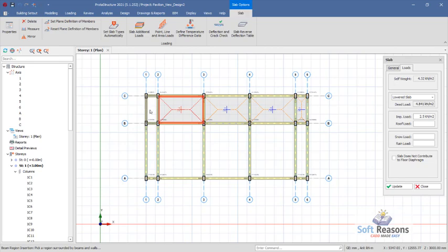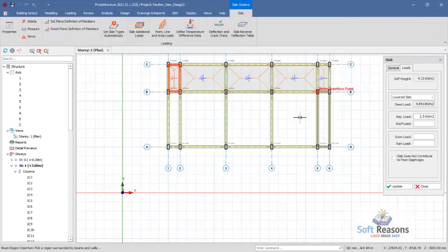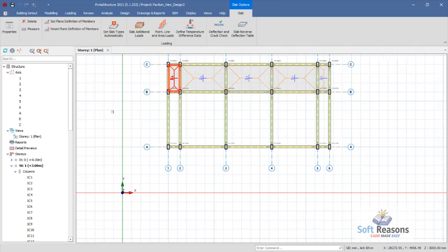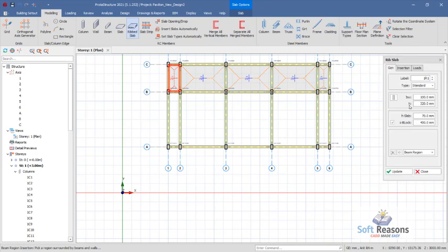Okay, alright, so having placed that at these provisions, we want to change the slab type, so we have to close this. Alright, get back to the modeling, and then we'll be considering rib slab right there. So click on the rib slabs. So for the bw of the rib slabs, we will be considering 125 right there. So for this we'll be considering 300 right there.